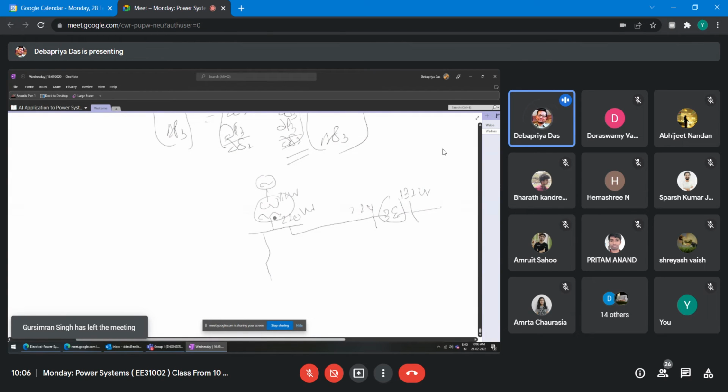So when we are studying load flow studies, we have not considered the transformer, because if I consider it, then you have to also create another bus bar. The things will become clumsy, and as a classroom exercise, you cannot do it. But every transformer has a tap setting.